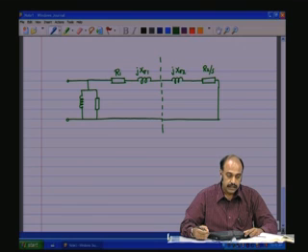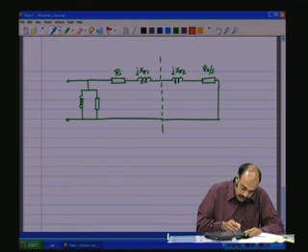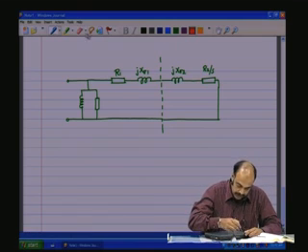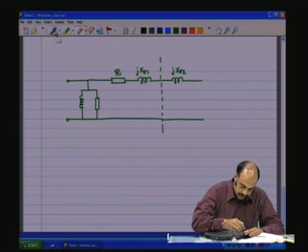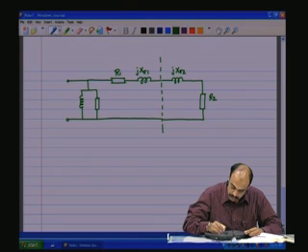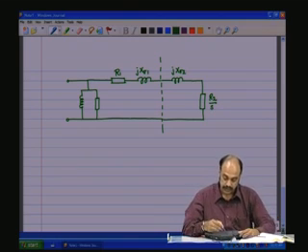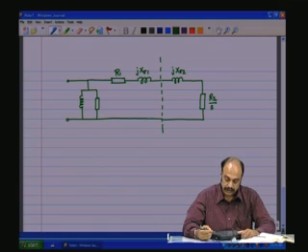So this becomes the effective equivalent circuit of the induction motor now, and to this we add the following things. Let me slightly modify this in placing, so that you will see this type in the textbooks, R2 by S. You will see that the S is figuring in the effective rotor resistance.